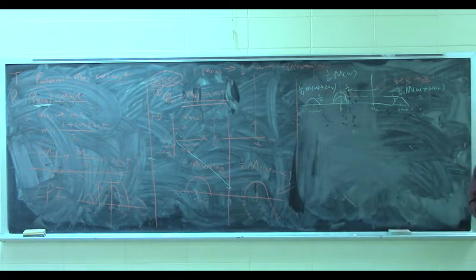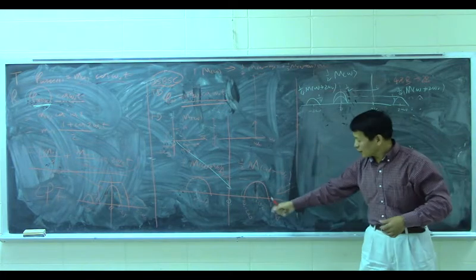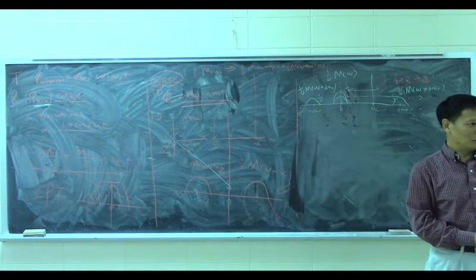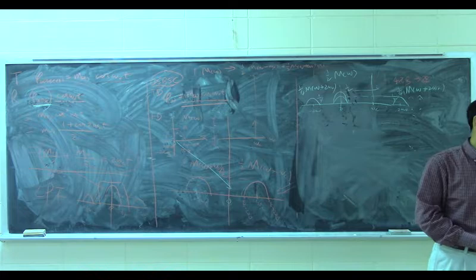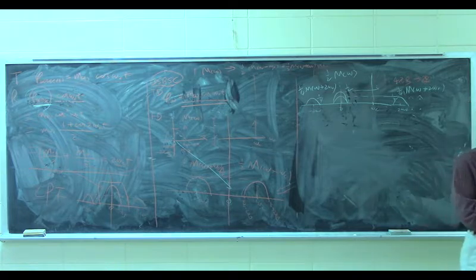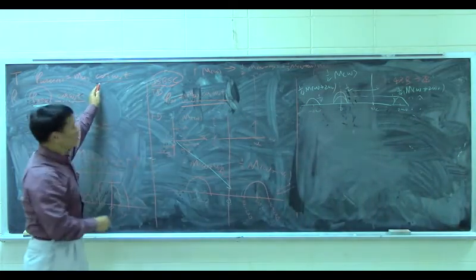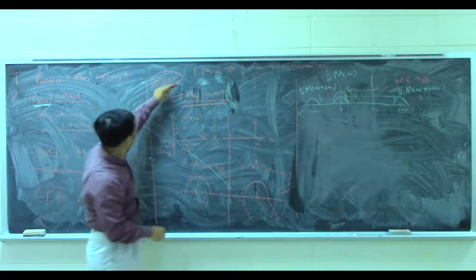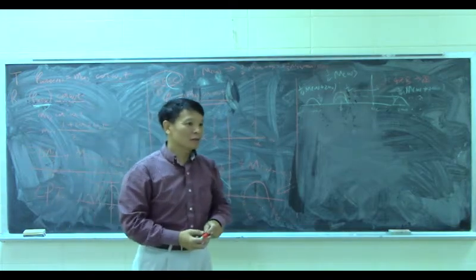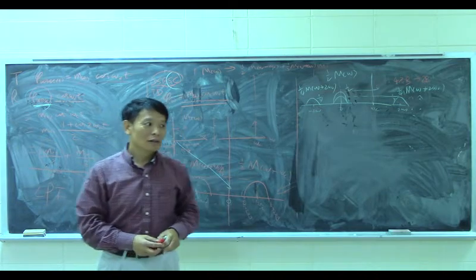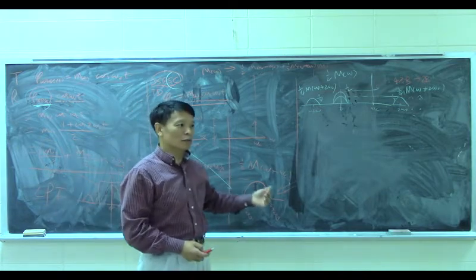See, we always emphasize that these two are exactly copied. Exact. Why do you need two? We can use only one. It seems like it's a result of something. The key here is we don't have this carrier information here. So that is the point of suppressed carrier, so you don't need to transmit this one here. And also it's easy to demodulate.